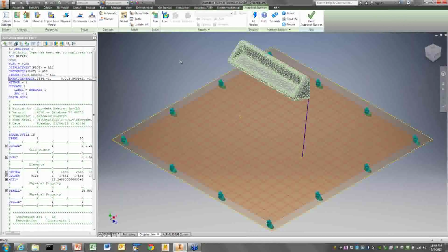I'll tell you what I do. I do a couple things. When I drop it, it's going to vibrate, and I will do that modal analysis, and when I drop it and I look at the transient results, I'm going to do a hand calc. I'm going to count peaks and come up with a natural frequency. When you run a modal analysis, we tell you what the modal mass is in different directions. And if I'm dropping this in the y direction, my part will have a number of modes that have high modal mass in the y direction. Those, especially the highest ones, should be the dominant frequencies in my response. So if I look at my output and it's not vibrating at those frequencies, then there's probably something wrong. So a quick modal frequency check is probably not a bad way to do it.